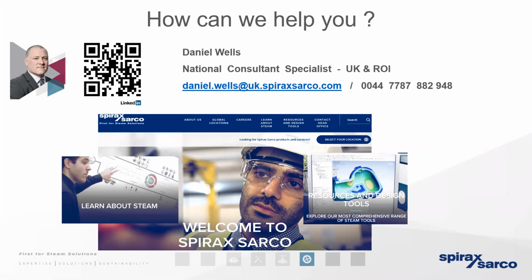It's for that reason that any existing heat exchanger will have that information badged on it or present on the thermal energy data sheet. It's important to bear in mind that the U value will only apply once the heat exchanger is brand new and free of scale or any other debris that could be creating a barrier to heat exchange.